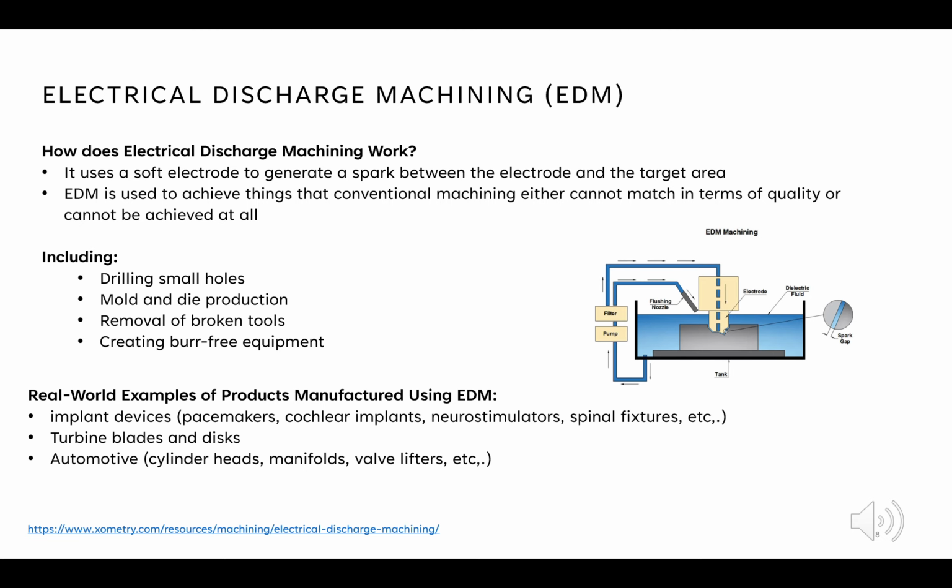Some common uses include drilling very small holes, producing molds and dies, and even removing broken drill bits from expensive parts. It also creates clean, burr-free components, which are especially useful in medical and aerospace applications. Real-world examples of EDM-produced parts include pacemakers, turbine blades, and automotive components like valve lifters and manifolds.